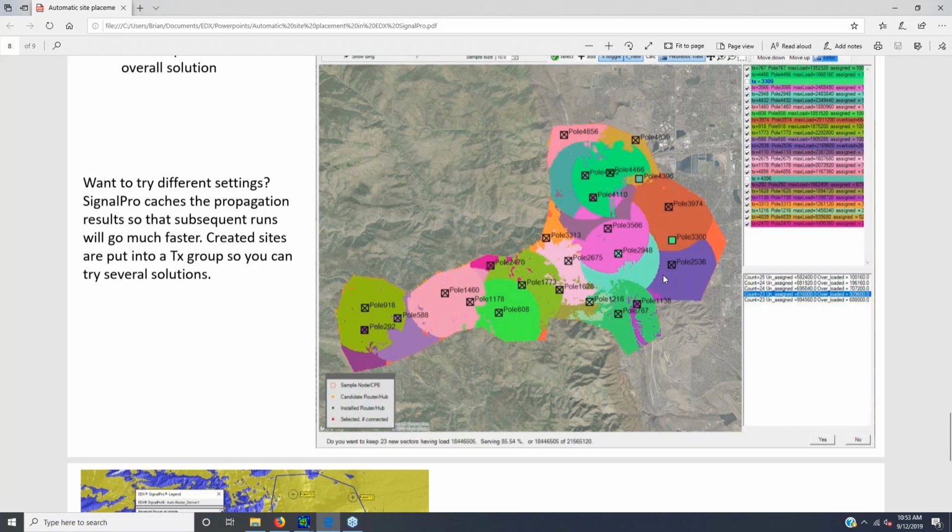However, I have seen the case a couple times where you can mount at one given height for cheap or free, and if you want to go up to a higher height on the tower, that's going to cost you more. But the tower location is the same. And in that case, you could put both of those pole locations in with a different height. The software is keeping track of the locations as an XYZ coordinate, so that they're considered distinct locations if they have different heights.